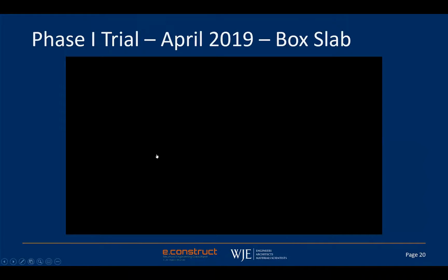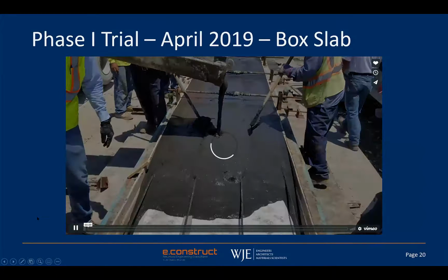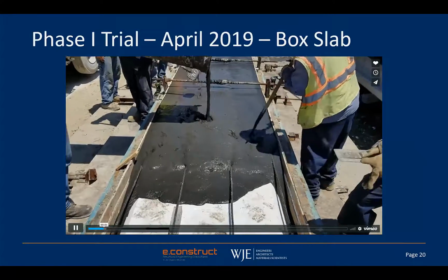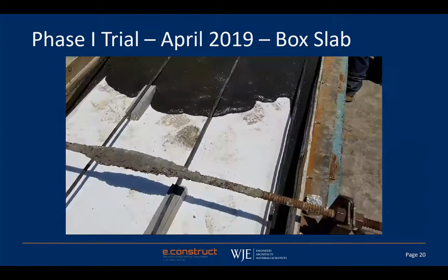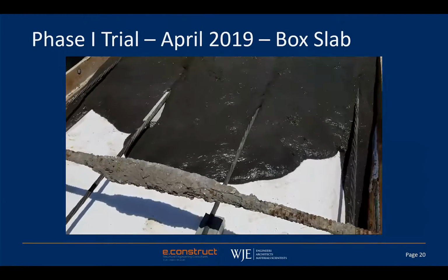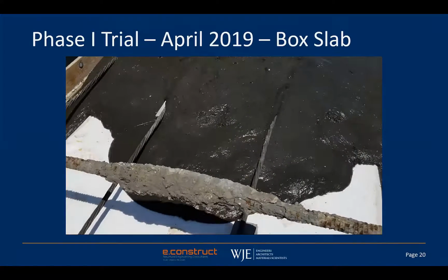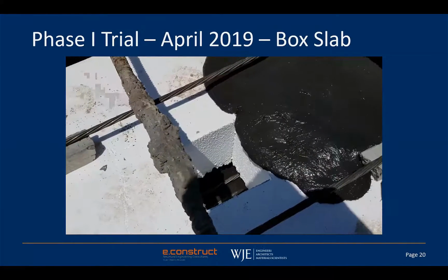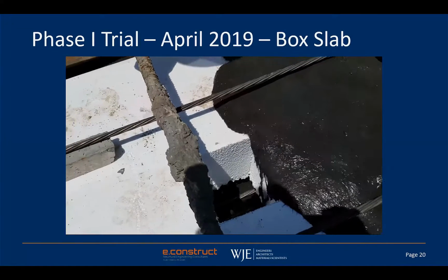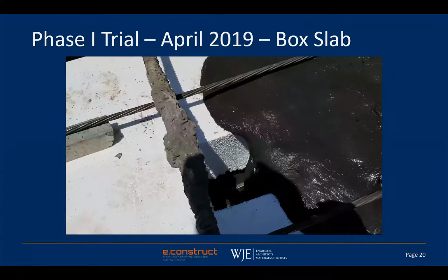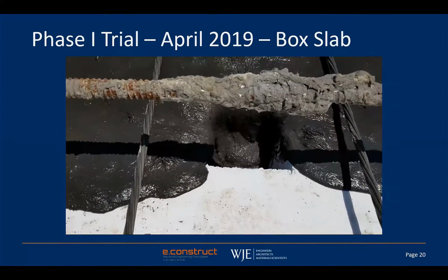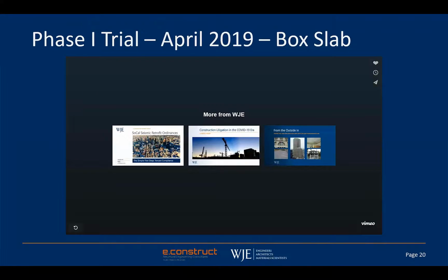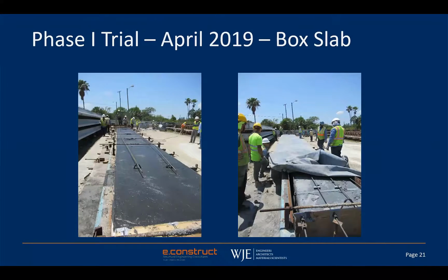All right, so I'd like to show you a quick video of placement of that box beam. So this illustrates the flowability of this material. You can see it kind of traveling along the top of the foam void former. You can see it flowing around down the sides, and it's a little hard to see, but in the bottom of that hole there, there is UHPC that's actually flown down around the sides and along the underside. So the full placement of this nearly 50-foot beam took about 20 minutes to accomplish.